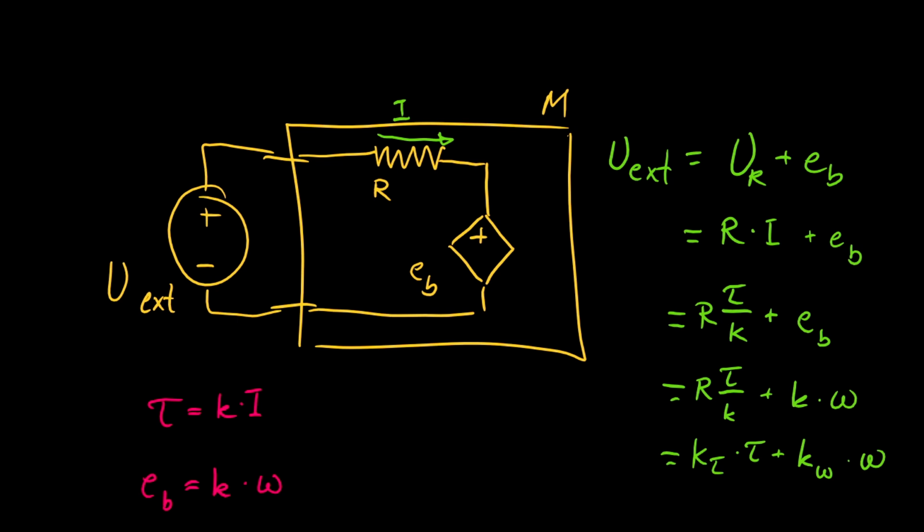But that just means that we could write PWM down here, and then the constants would change slightly because now we're not working in voltage, but rather a percentage. That doesn't really change much, as it's only changing the value of the constants. So essentially you can make a feedback loop with the speed in order to set the correct voltage to achieve the torque that you want.